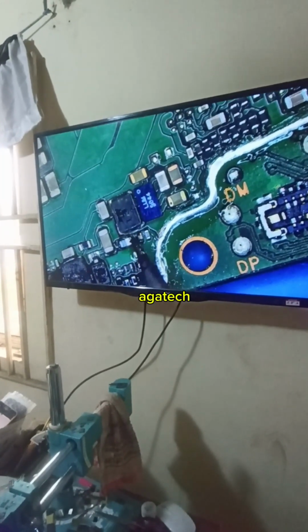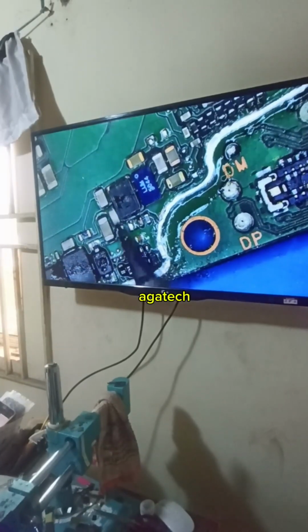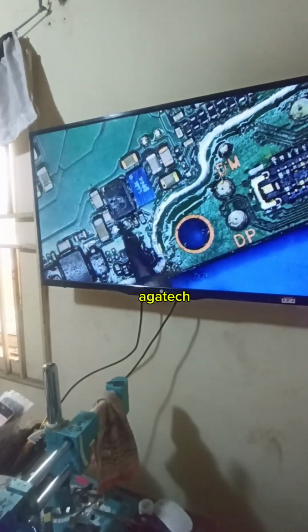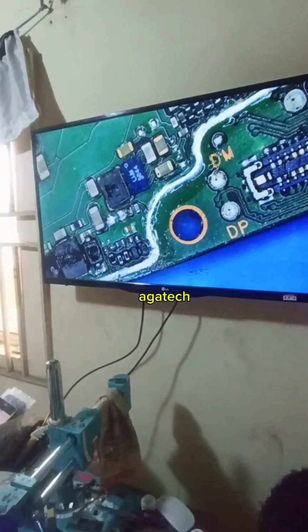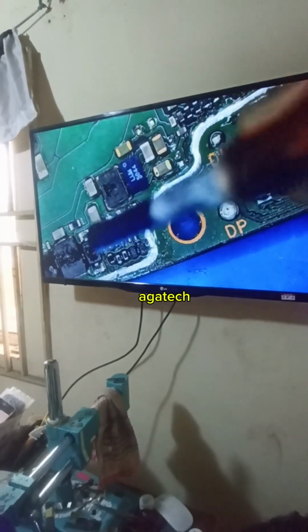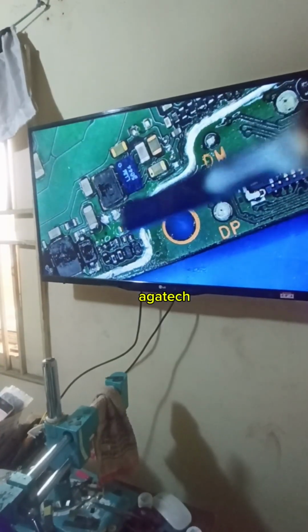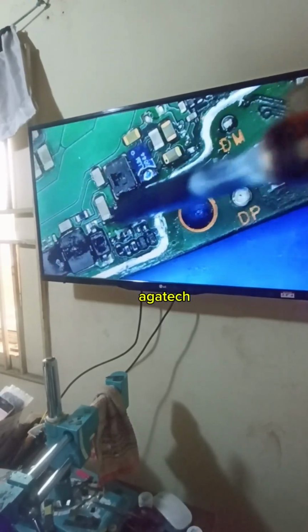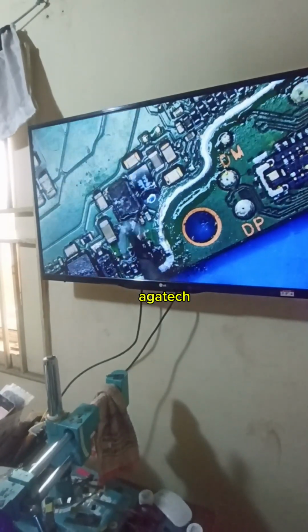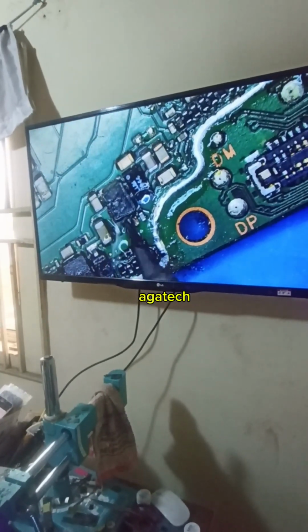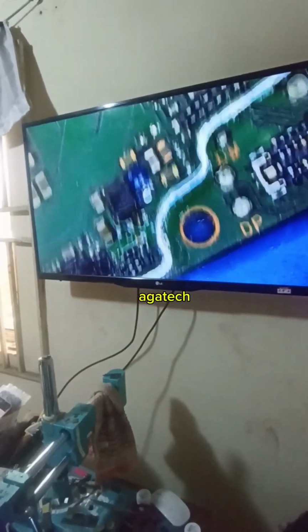Okay, the fuse is bad. I can easily just use a jumper. I can put a wire there. If I put a jumper wire there, it will still work, but it's not wise, because whatever spoiled the fuse would have spoiled something else if a jumper was there. So instead of putting a jumper, we'll put another fuse.